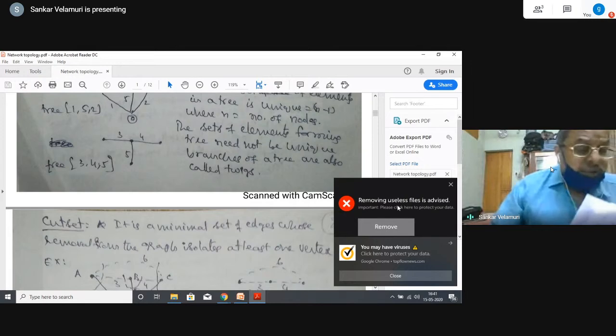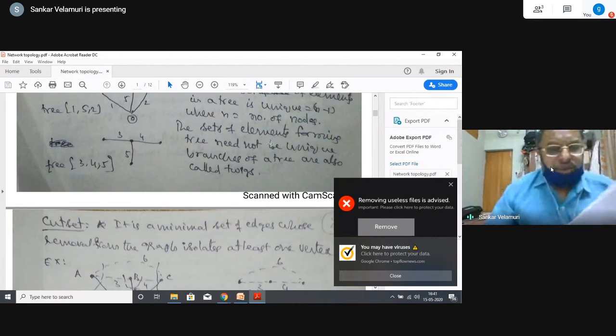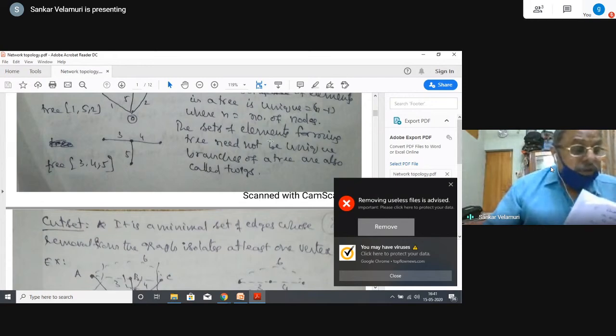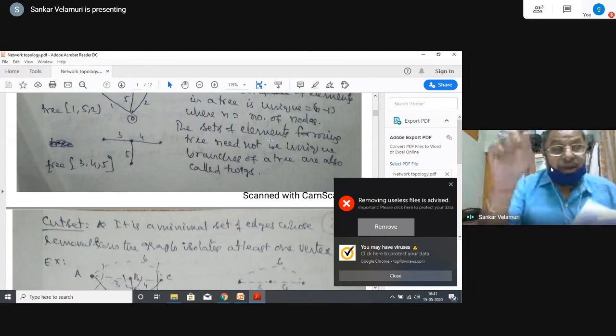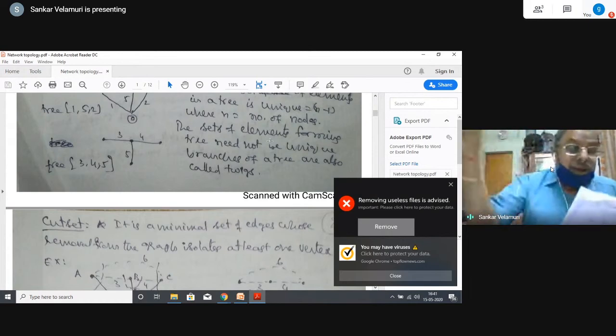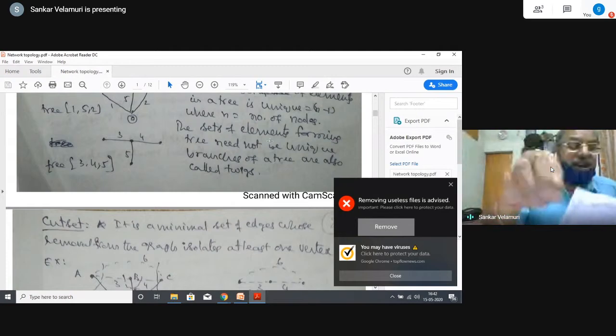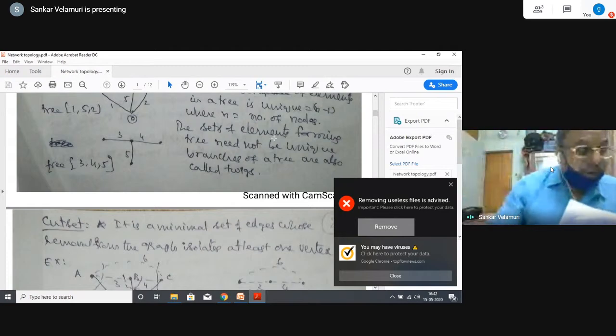So, next question. In a graph, sources are replaced with internal resistance, but dependent sources, how are they taken, as short circuit or open circuit? This is a very good question, and only later did I understand the importance of this one. Only independent sources are to be replaced. Dependent sources cannot be replaced. They have to be retained as they are. That is what I mentioned in Thevenin's theorem and Norton's theorem also. They have to be retained as they are because they are dependent. How they are dependent, what their nature is, if such a situation occurs, that is how we have to solve the problems.